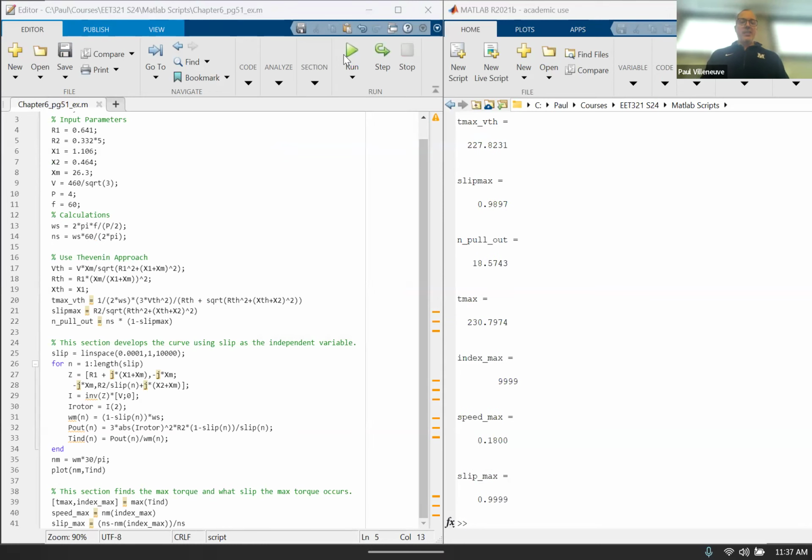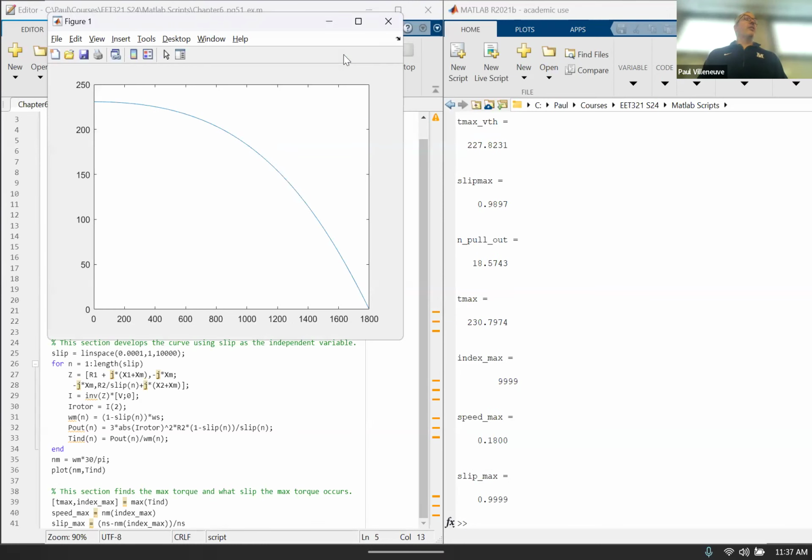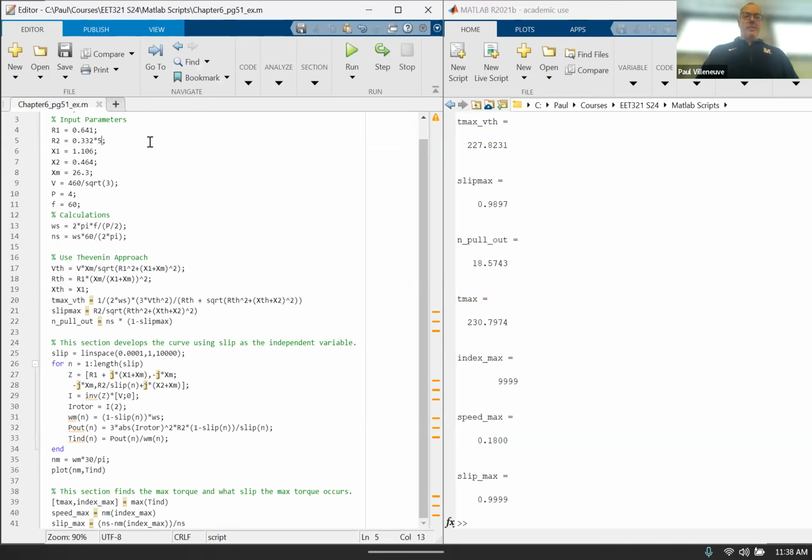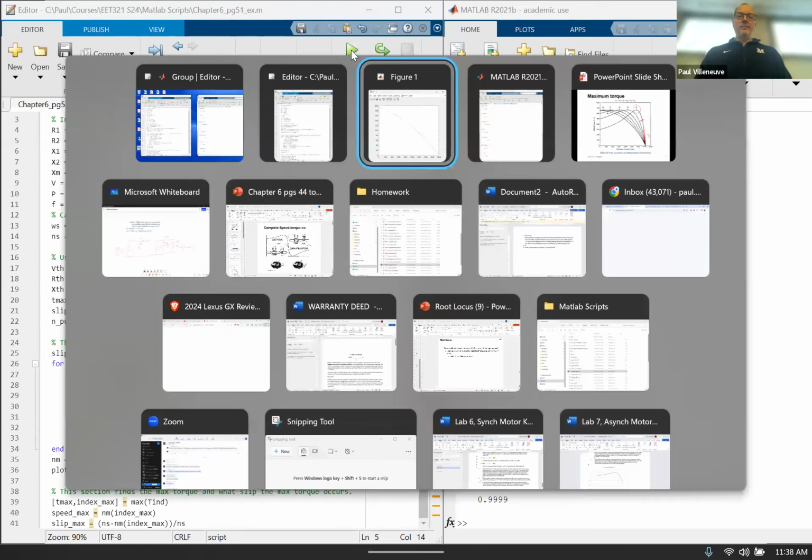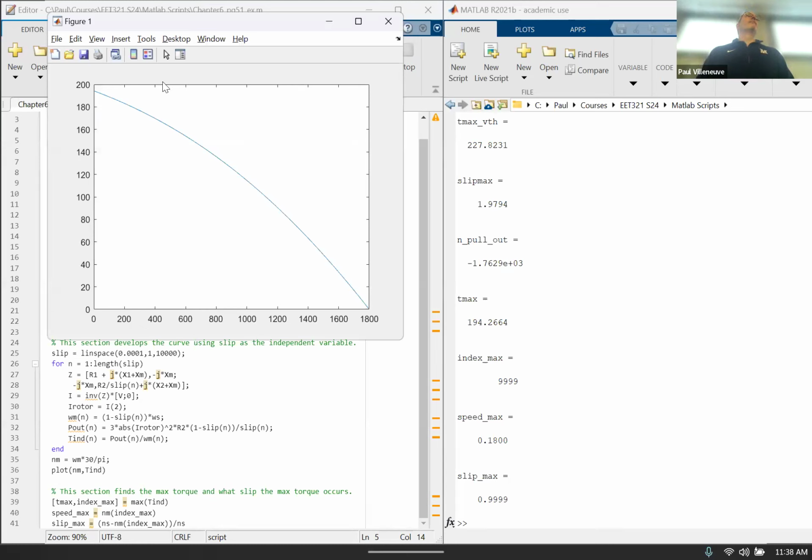It actually allows us to change the characteristics. So 5 times the resistance looks like we get all the starting torque right here. Remember we said 231? What happens if we go to 10 times? Straight line? Take a look. Becoming a straight line, but now look what we've done.